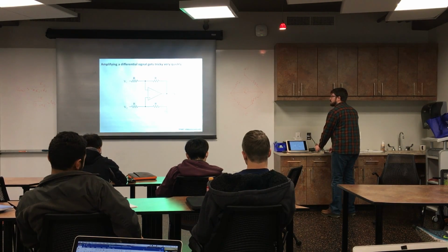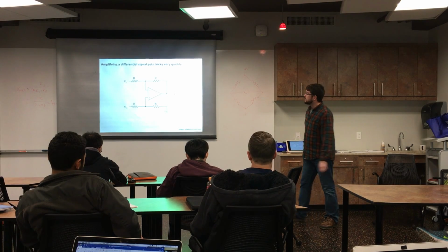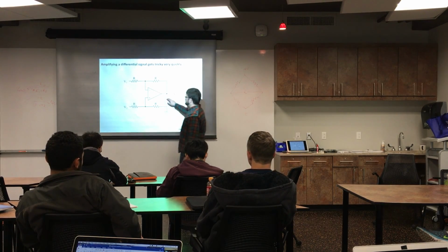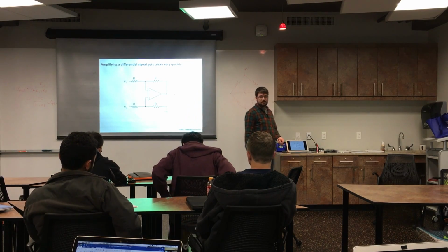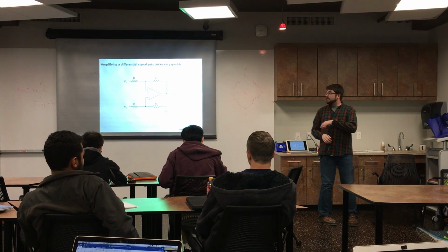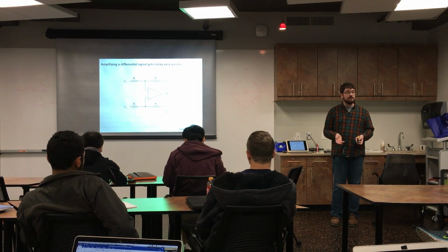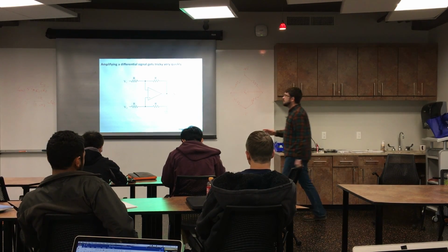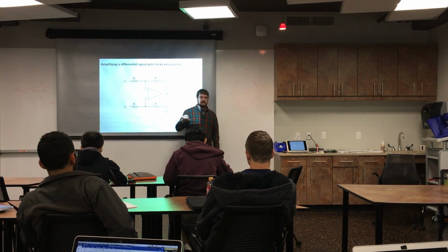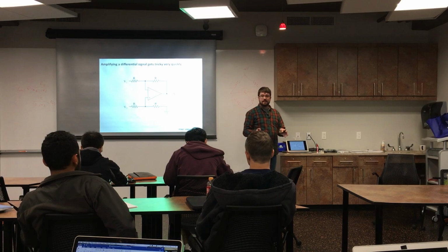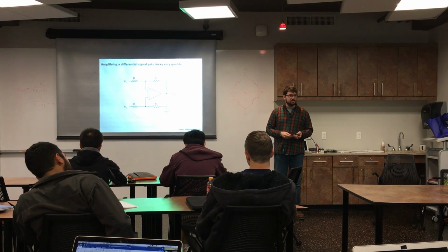Well, it gets a little bit more complicated, and to do that with a regular operational amplifier, you have to create these two divider networks, one in the feedback loop and one to divide the input that it's comparing to. That looks great on paper, and you say it's just 4 resistors, and we had 2 resistors before. This isn't hard to implement. The catch is, if these resistors are not perfectly matched, you will get an input offset error. And if you have significant amplification, you just blew your entire voltage range on input offset error.